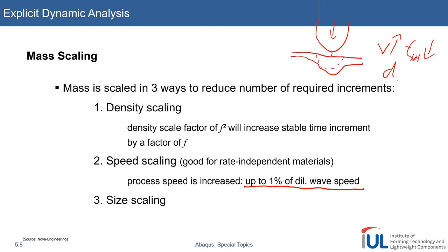And if you increase the punch velocity too much, you will see exactly those kind of dynamic structural responses, which are only based on the elastic properties of the material. Even if the elastic response can be rate dependent, this is rarely used but could be.